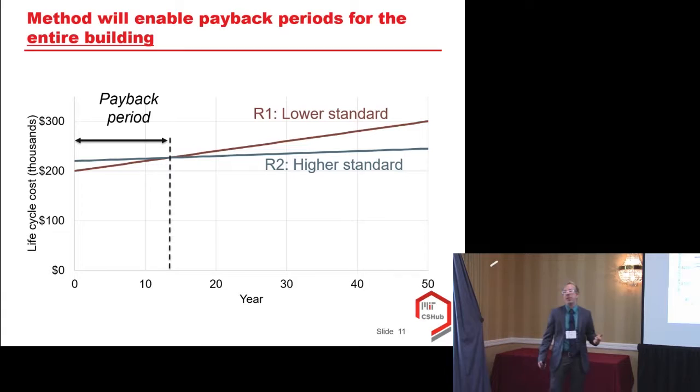We found through surveys of architecture firms over a couple of years that the payback period is a metric that really resonates as people are making decisions in terms of designing their homes. Often you'll hear about, should I put a solar panel on my roof or not? Well, what's the payback period, right? So the same sort of terminology is what we're going to use here to think about the payback period for designing my home to be more resistant to a variety of natural hazards. And so we're seeing that as the time when the cumulative costs of the lower standard over that life cycle overtake that of the higher standard.